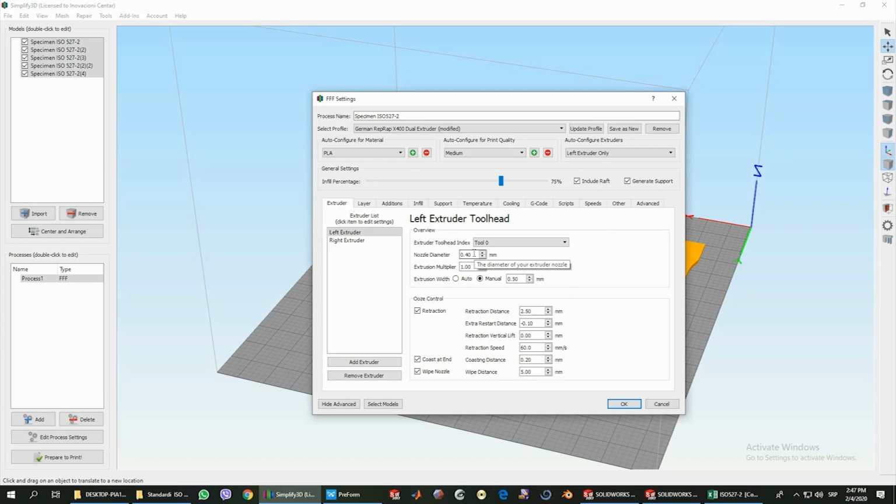This is the value of width of material extruded from the nozzle. We have 0.4 millimeter nozzles on the extruder installed right now. You may have 0.2 for more detailed 3D printing, but if you want to print in more detail, it will last longer, so the optimal nozzle diameter is at 0.4.